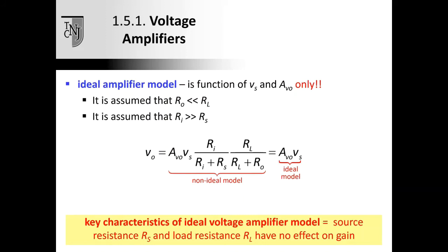We talked about that a lot in ELC251-01. And then also, the output resistance will essentially be a short circuit. So for this representation, V out is equal to our constant gain times Vs. So that's a quote-unquote good or linear version of the amplifier.